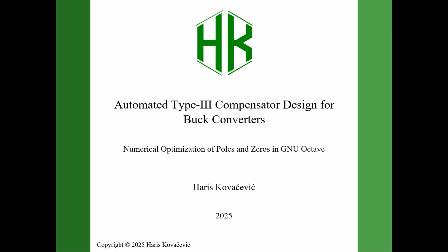Using GNU Octave, we formulate the compensator design as an optimization problem and automatically compute the Type 3 parameters for a buck converter. This is not a replacement for theory, it's a practical tool that builds on it and dramatically speeds up real world control design.